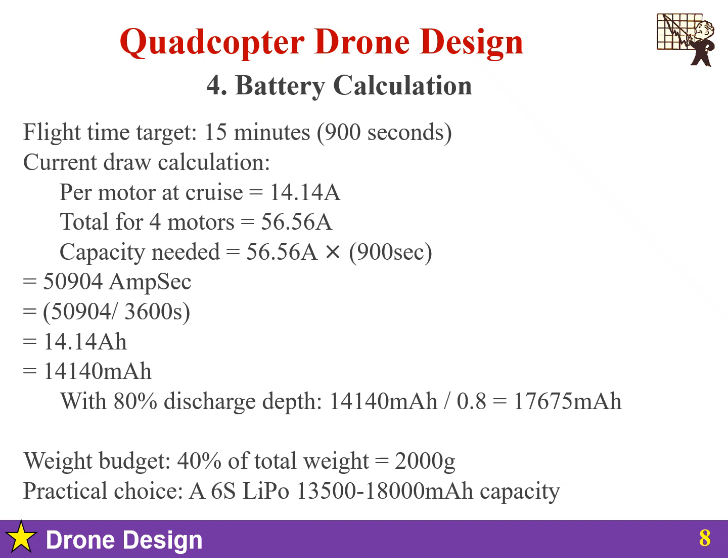Most professional batteries are rated between 25 to 35 C continuous, providing substantial margin. However, verify manufacturer specifications. Some manufacturers overstate C rating significantly. Battery management systems. At this investment level, proper battery management isn't optional, it's mandatory. Balance charging for cell health, voltage monitoring per cell during flight, temperature monitoring during operation, proper storage voltage maintenance, that is 3.8 volts per cell, cycle count tracking for preventive replacement.